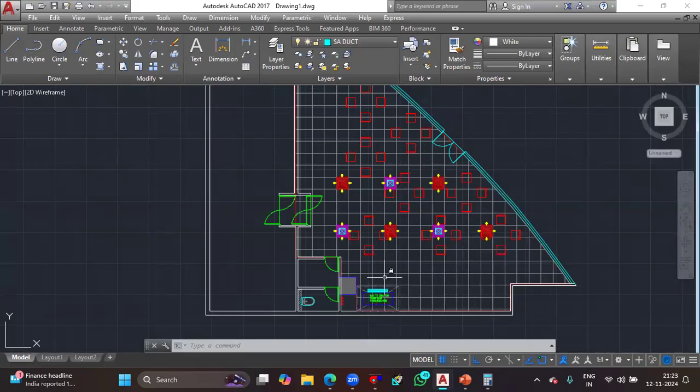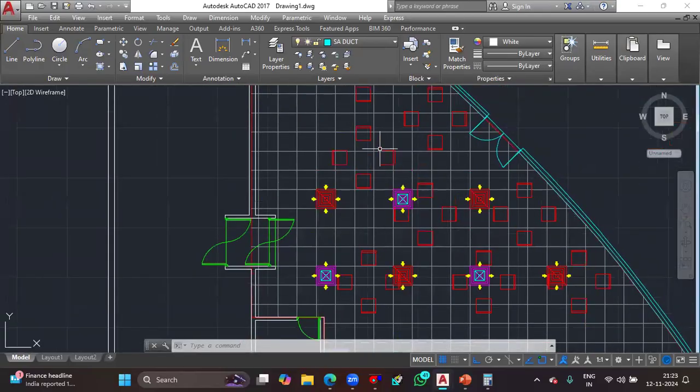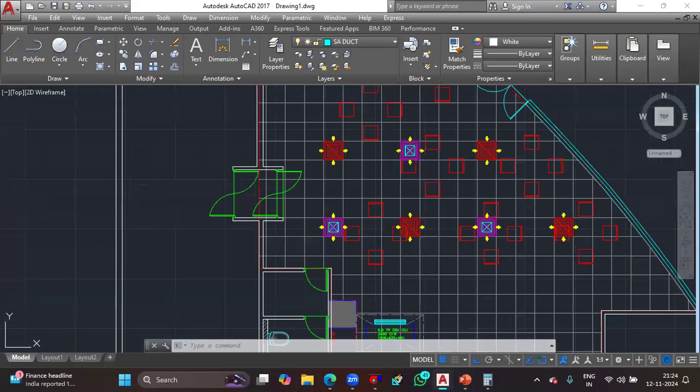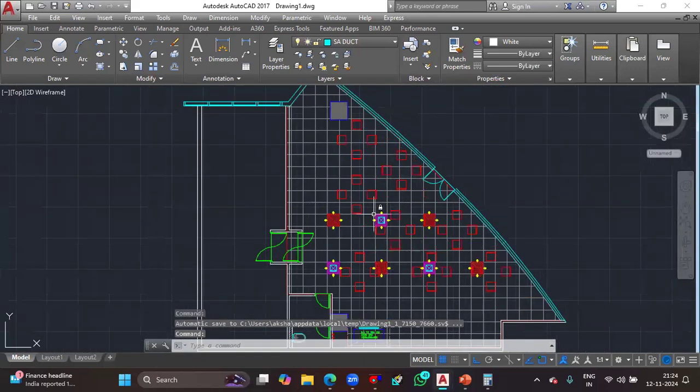You can see right here, guys, if I take a duct, can I connect this duct to the diffuser? These things must be considered while placing these diffusers. Once again, each and every table should get proper air conditioning. That means the supply should be placed across the occupancy sites itself. So that is also a factor.